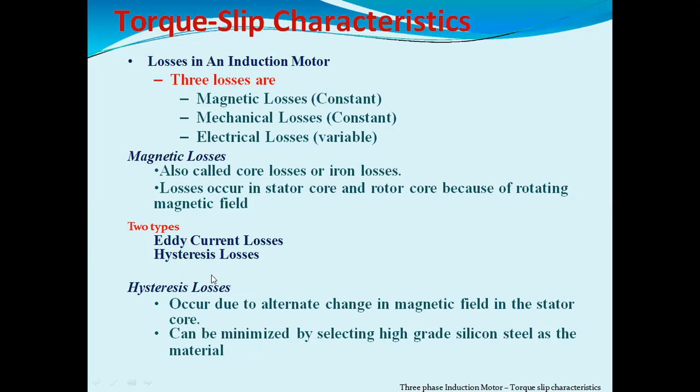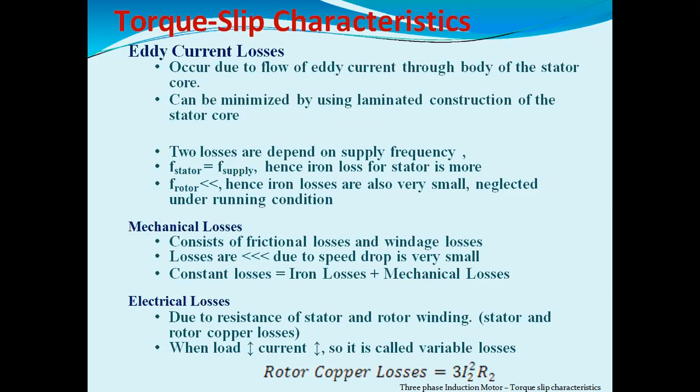We can minimize hysteresis loss by selecting high grade silicon steel instead of the iron core. Using silicon steel minimizes the hysteresis loss.